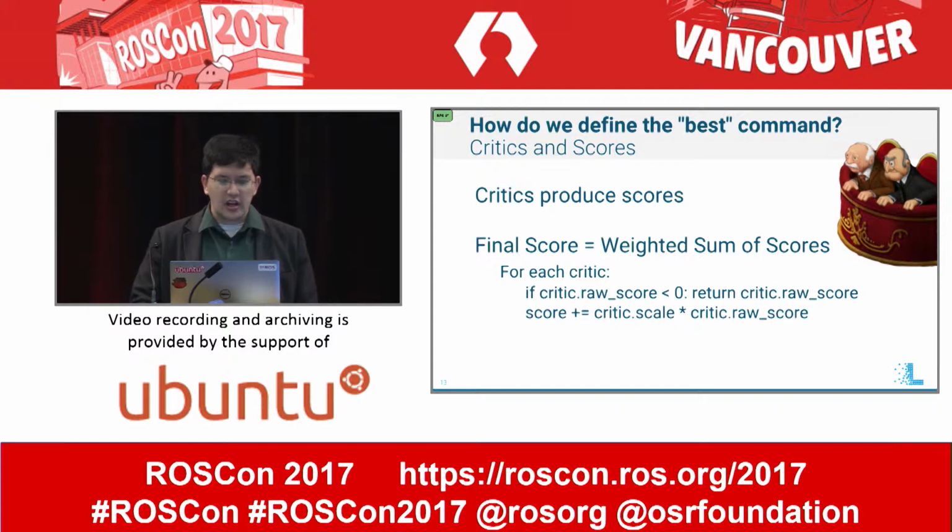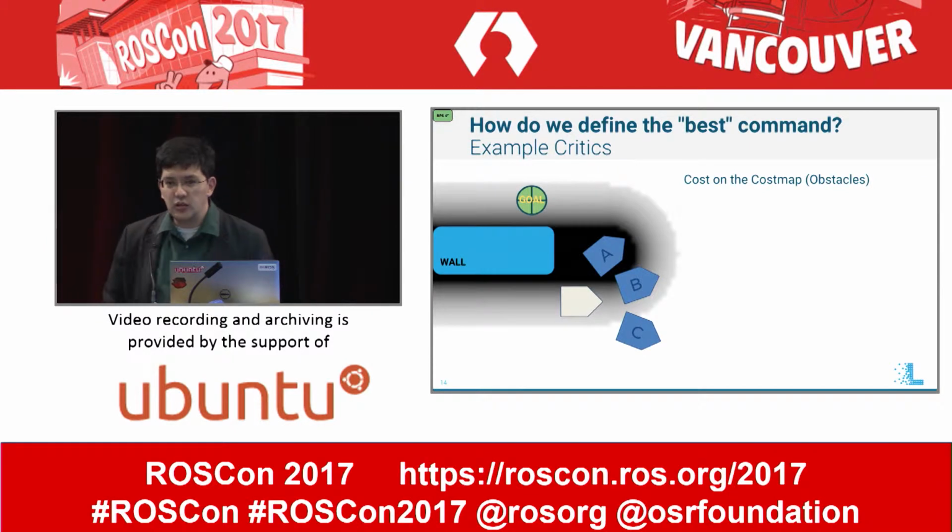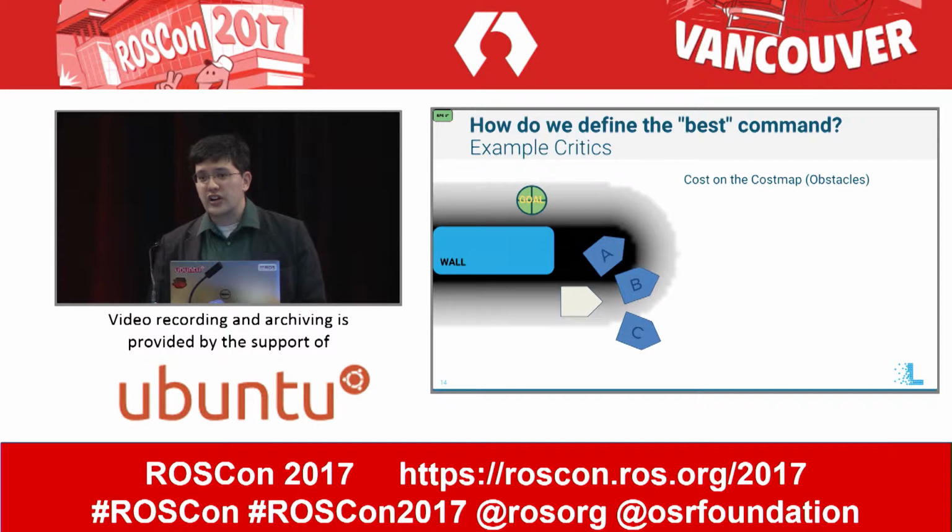And so taking a look at some of the critics that are available, one of the key ones is the obstacle critic, which looks at the cost on the cost map. And so if any of the poses in the trajectory that you generated are in collision according to the cost map, then we reject them out of hand. Otherwise, we just use the cost from the cost map.